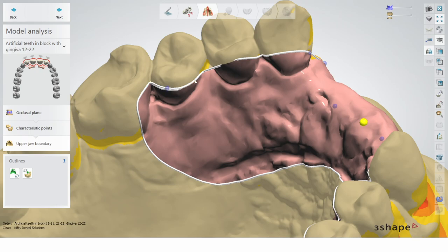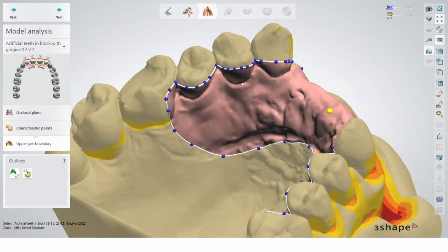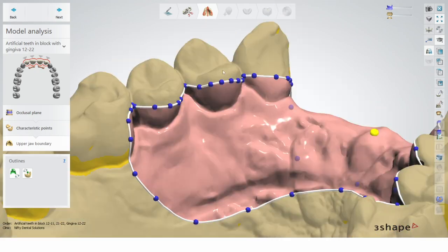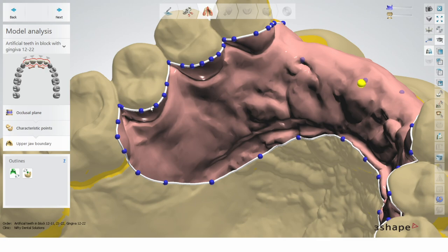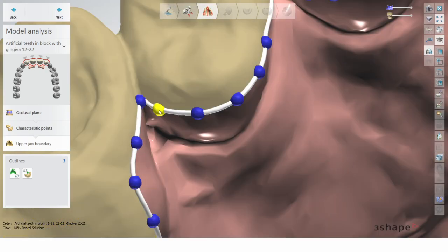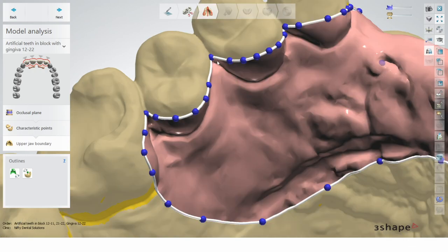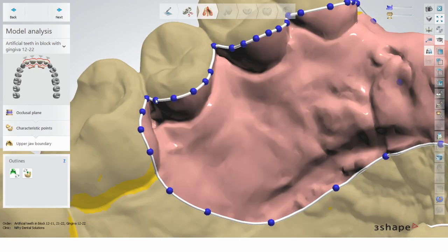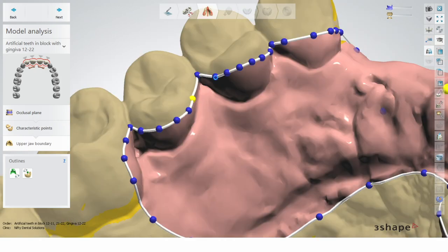So just by drawing the line, which is quite cool. But if I now get off from the fast edit, you can see where I've been fast editing, the dots are quite a lot. If you look on here, they're even overlaid. So this makes the software a little bit heavy. So my advice is, if you can, just use the dots.